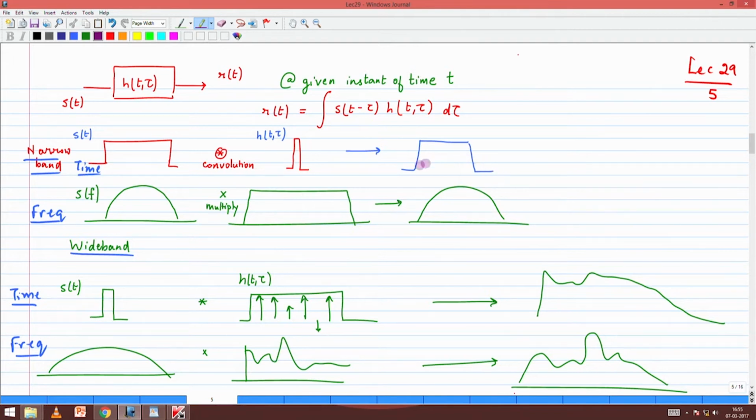These are the flat fading scenarios where it is easy for us to build the receivers. On the other hand, for wideband signals, the channel dispersiveness is much longer than the duration of a symbol, which means that the symbol gets extended and distorted, and successive symbols will overlap, causing intersymbol interference. This can be represented in the frequency domain as the spectrum of the input signal plus a frequency selective behavior of the channel, which distorts the frequency spectrum.